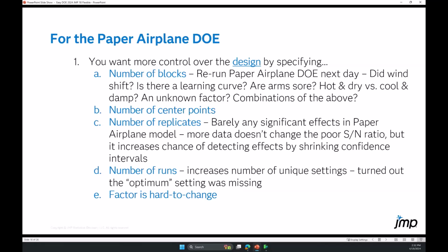Now, what it also means is if it is significant, you've got some detective work to figure out why the results are so different from day to day. So it's a cheap solution. It only costs you one more run typically in a design to add a block. And so we highly recommend it when you have this situation of restricted randomization between "I did all this stuff yesterday, I'm doing all this stuff today," and what we want to know is, did the process shift between those two groups?